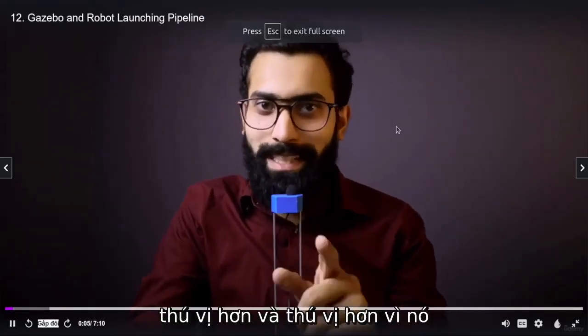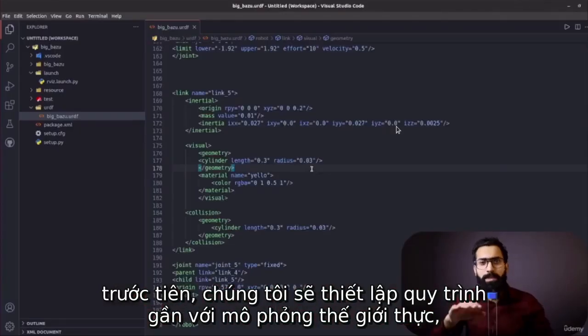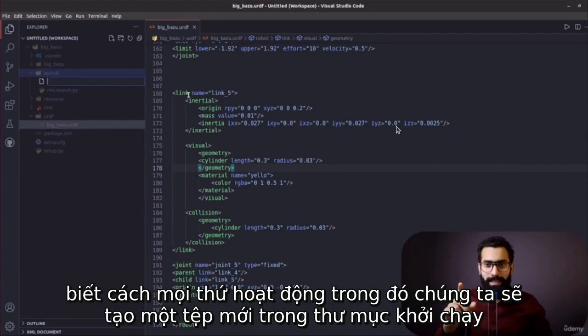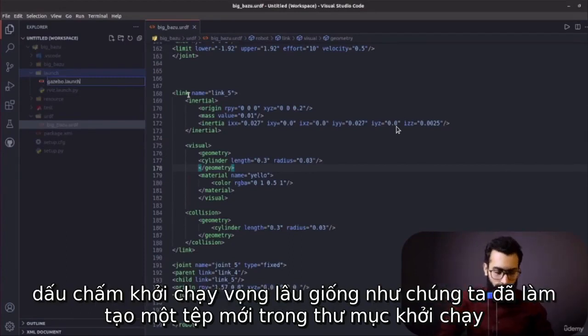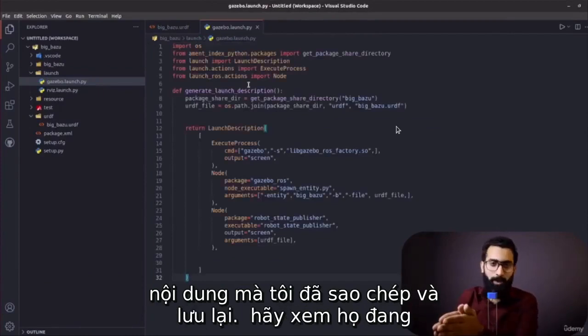Now Gazebo is more exciting and more interesting because it deals with physical properties and is very close to real world simulation. We are first going to set the pipeline of launching Gazebo. I will explain how things work in that. We are going to create a new file in the launch folder, gazebo.launch.py, same as we did with the RViz. I'm going to bring in the contents that I've already copied and save it. Let's take a look at what they are saying.